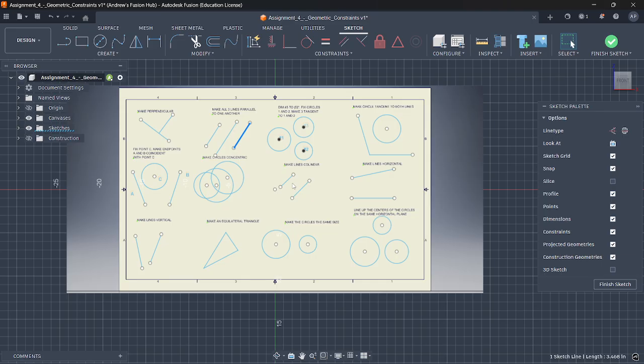Still zero, but. So you have to use the fixed constraint first to make sure that the circle doesn't move. That will block the edge lines. And then now it should pull. Yeah. And then you edit the sketch.